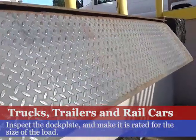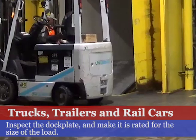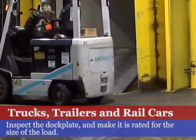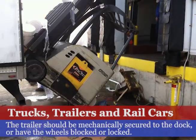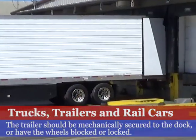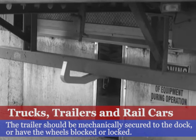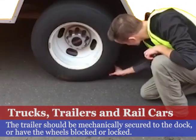Inspect the dock plates. Make sure that they are in good condition, and have been installed securely. The dock plate must be rated for the size of the load crossing it. A loose trailer or rail car can be dangerous. Make sure the trailer is mechanically secured to the loading dock. If that is not possible, use another means to block or lock the wheels.